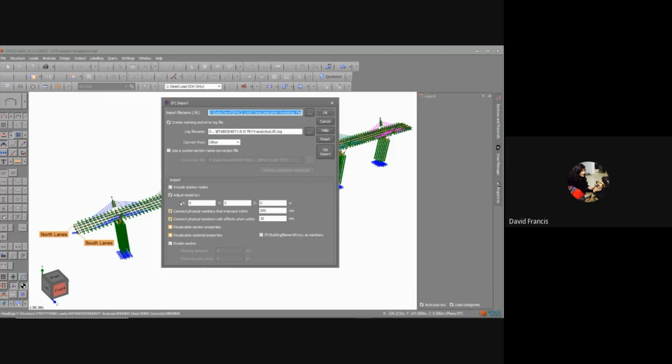So here we have a number, but there are some issues with the Midas conversion, and you'll see that we've got an option for Midas, and so we've corrected the errors. I haven't done this for two or three years, so we'd probably have to review it because they'd be updating the IFC4 export options, and there may be different issues. So we try and correct the errors in the file.